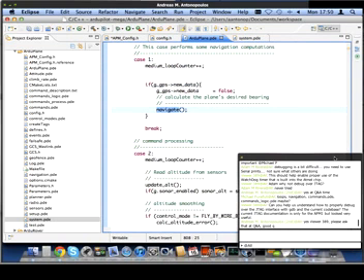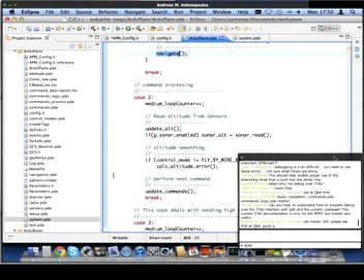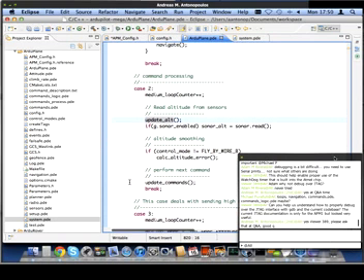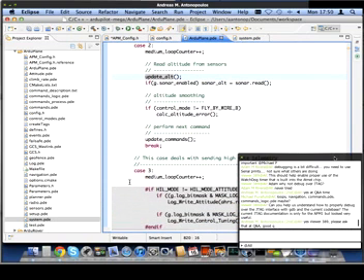So you can see, for example, that the main navigation code updating the direction that we're trying to fly the plane is called at 10 hertz, whereas the stabilization, the setting of the servos, is called at 50 hertz. We can also see things like the altitude read from the sonar, if you've got a sonar, and also from the barometer, that's called at 10 hertz. Now that can be a little misleading, however. I'll just tell you something about that because that's been updated recently.